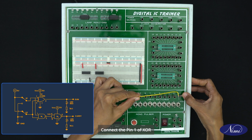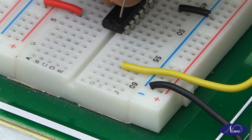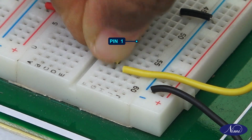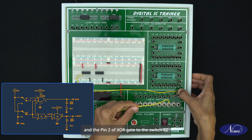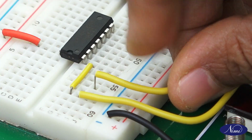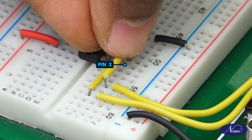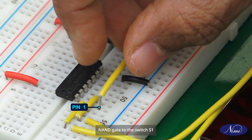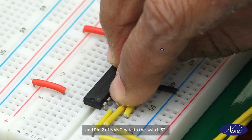Connect pin 1 of the XOR gate to the switch S1 and pin 2 of the XOR gate to the switch S2. Connect pin 1 of the NAND gate to the switch S1 and pin 2 of the NAND gate to the switch S2.